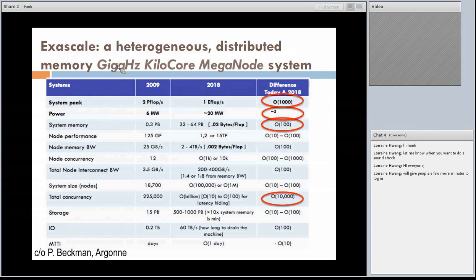The idea on the top says that rather than increasing the clock speed, we could get more of these cores. And so again, we're getting 4 gigaflops, but we're doing it using 4 cores. But now instead of taking 64 watts, because the power is proportional to the frequency cubed, it would just take 4 watts. And so the result of this is that we don't want faster and faster clock speeds. What we want is slower clock speeds and more cores. So as we talk about having a billion cores, this is a big reason why.